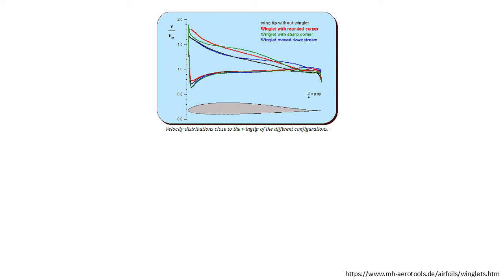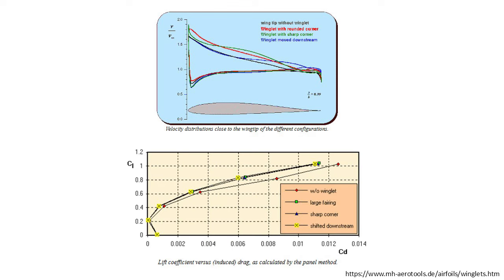The result of adding a winglet will be just better than a wash on the overall non-lift induced drag. What we're talking about here is a slight decrease in form drag, but we're still ultimately increasing the wetted area of the aircraft by the addition of the winglet. The results of this study would indicate that a blended winglet shifted slightly downstream will perform best, but only by a small margin. As would agree with the relationship between induced drag and lift coefficient that we looked at earlier, any winglet becomes very effective in decreasing drag at high CLs.